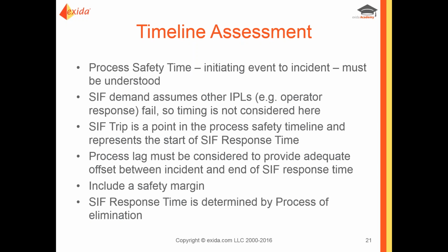We also want to include a safety margin. Because this is an engineering judgment and a calculation, there is no one perfect answer for the timeline assessment. So it is good to include some kind of safety margin, and that is a judgment call. And then, of course, we calculate the SIF response time simply by eliminating all those other values that we can determine.